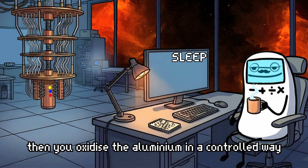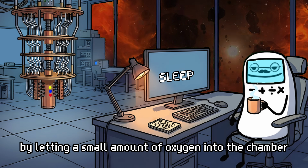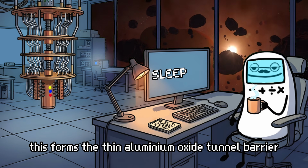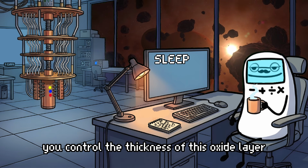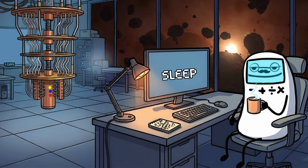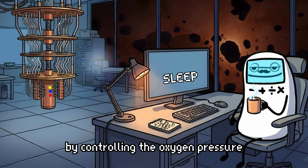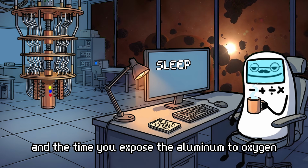Then you oxidize the aluminum in a controlled way by letting a small amount of oxygen into the chamber. This forms the thin aluminum oxide tunnel barrier, which is the insulating layer in the junction. You control the thickness of this oxide layer, and hence the tunneling strength of the junction, by controlling the oxygen pressure and the time you expose the aluminum to oxygen.